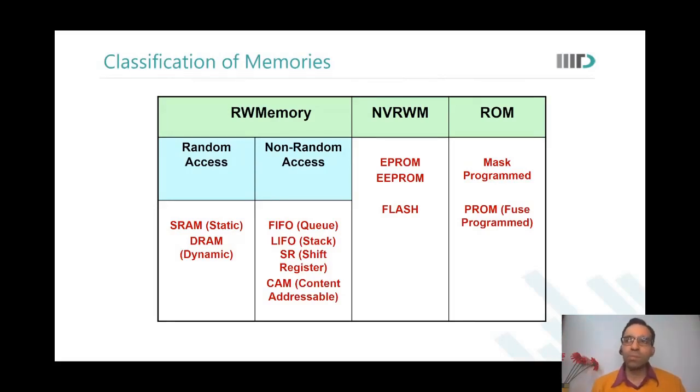ROMs are again, typically any die would have at most one ROM. Whereas where we talked about SRAMs, every die would have hundreds of SRAMs. Some would be for register files. Another set would be for L1 cache. Another set would be for L2 cache, L3 cache, and so on. ROMs, typically the entire chip would have only one. That too only for the purpose of storing the boot code, which was pre-established before the system was even manufactured.